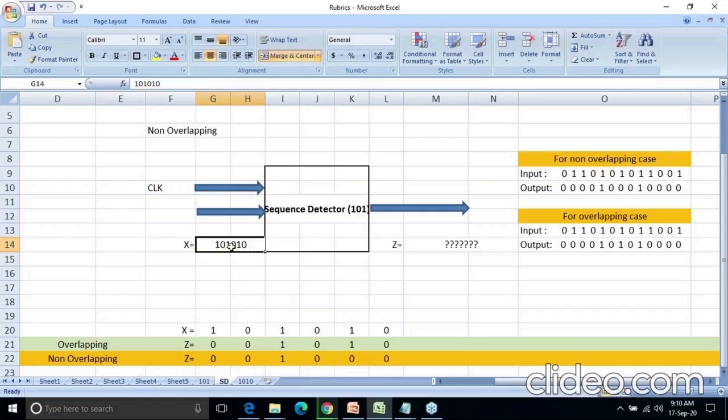have given. Now this is not coming at a time. Means if I have given 6 bits over here, those 6 bits are not coming in parallel. Just keep that in mind. How does it come? When the first clock is given, the first bit will be applied, then again a clock is given, the second bit will be applied, the third clock is applied, the third bit will be applied. So although you can see this as a 6-bit value, it will be coming one by one. It is a string of zeros and ones. Meaning, all the bits come one by one when the clock is applied.